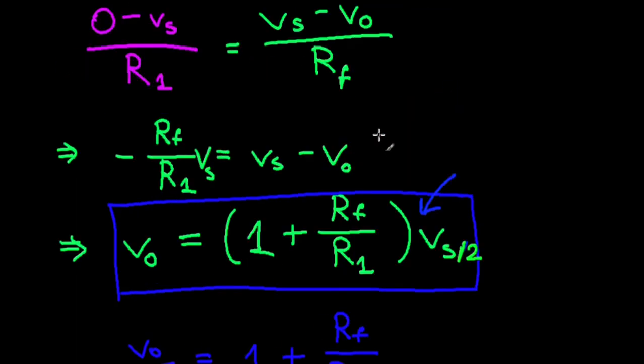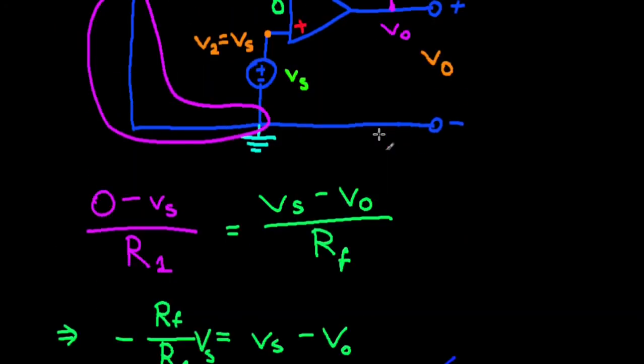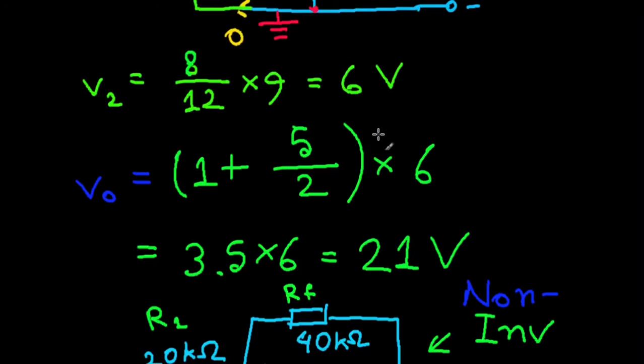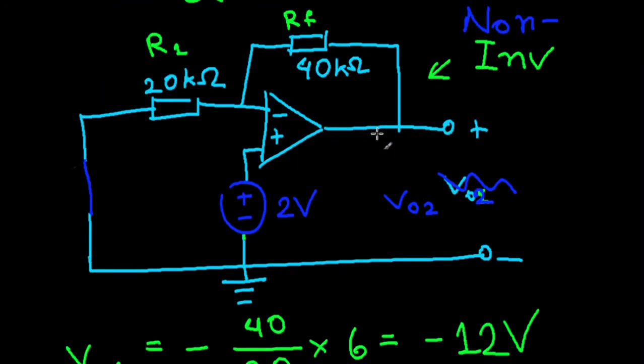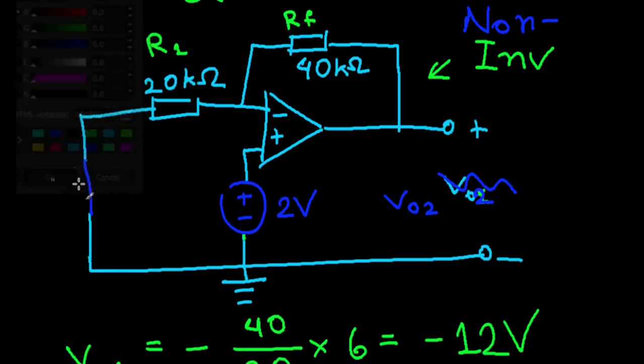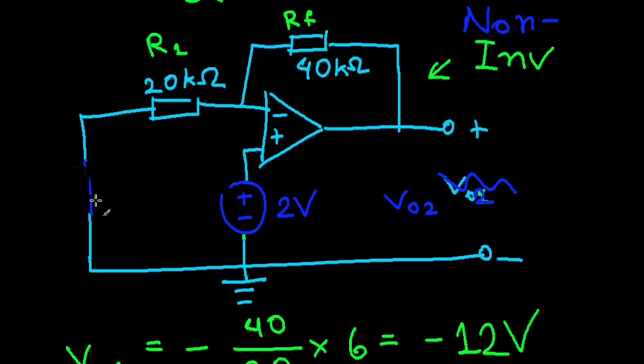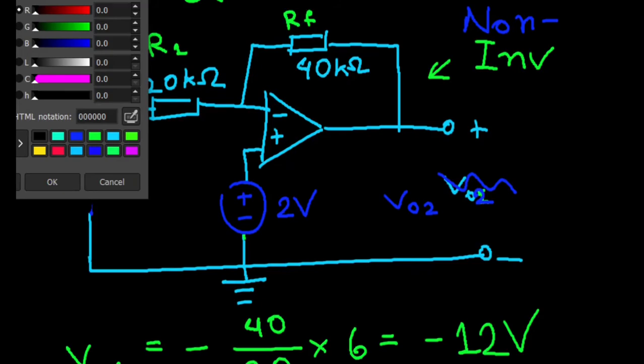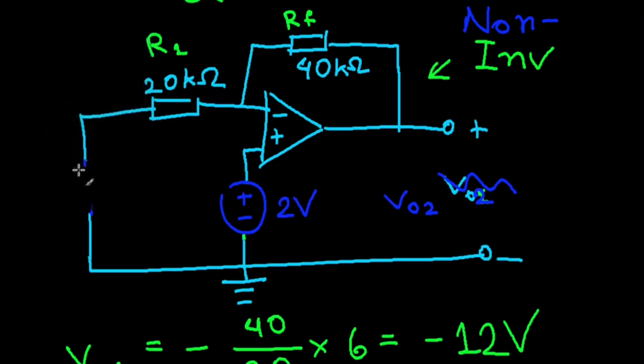So very interesting, we got our result by applying both the types of op amps that we have seen so far, and that's why I think this was pretty interesting. One more thing is, you can actually solve this even without knowing these two. I mainly just wanted to show you that you can use superposition and all that, because an op amp is actually a linear circuit element.